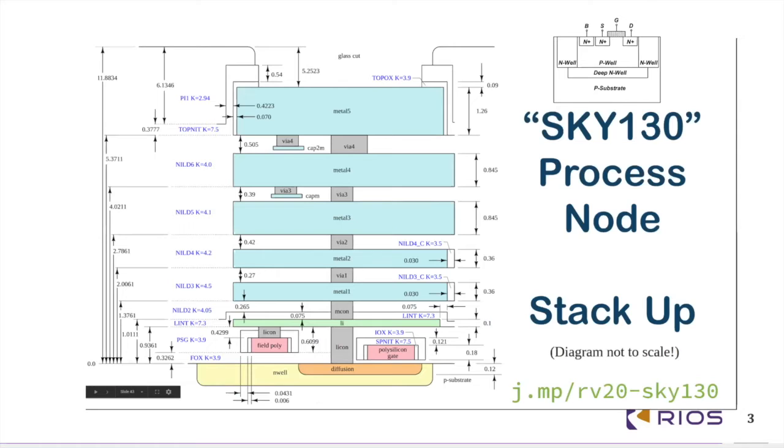And PDK is actually the symbol of the manufacturing flow in the foundry. You can see in this picture, the PDK describes some physics arguments of semiconductor craft, and our design is limited by these physical rules. In Skywater 130, we can use 5 types of metal for connection, and the smallest size is 130 nanometer.